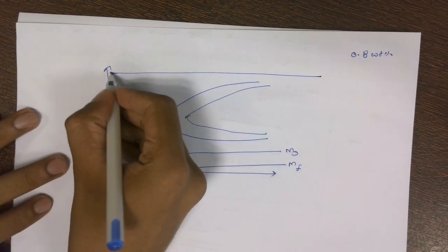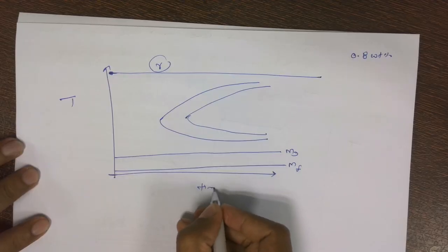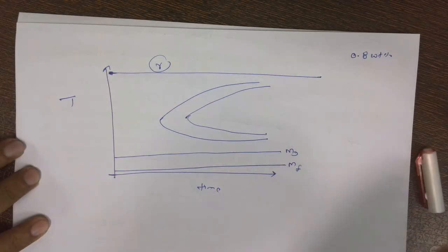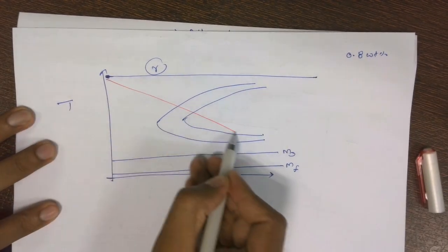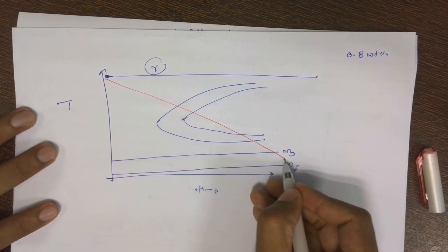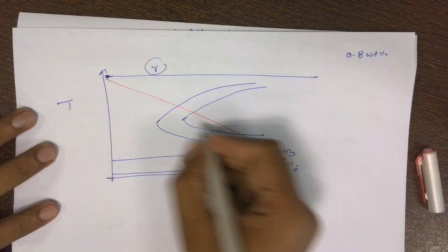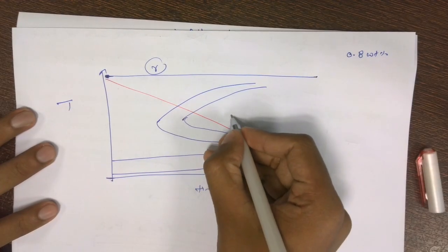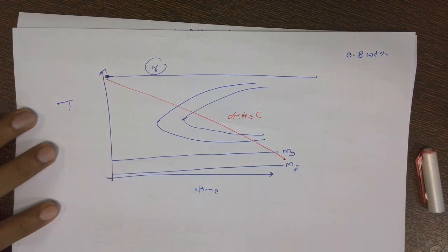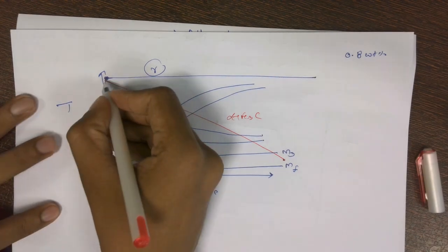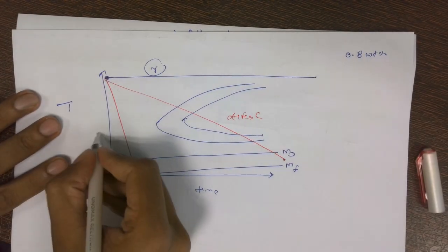One can say, will I get the martensite? I'll get a lot of phases. Austenite will convert to ferrite and cementite, right? I will not get the martensite. What do we have to do to get the martensite? We have to quench it. Fast cooling, right? Quenching. This was case 1, and case 1 is a failure because we'll not get the martensite, we'll get some other phases. Now, this is where we are getting the martensite, the second one.